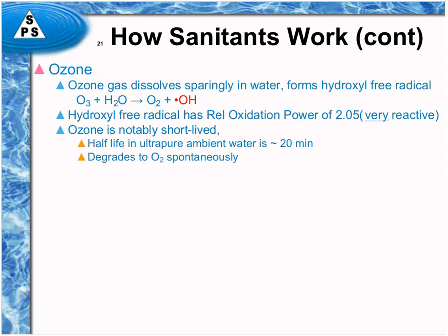The hydroxyl free radical is exceptionally short-lived, but the ozone itself is also short-lived. It has a half-life in ultra-pure water at ambient temperature of only about 20 minutes because it degrades spontaneously to oxygen gas. It's easily removed by UV radiation, which actually enhances that degradation process.